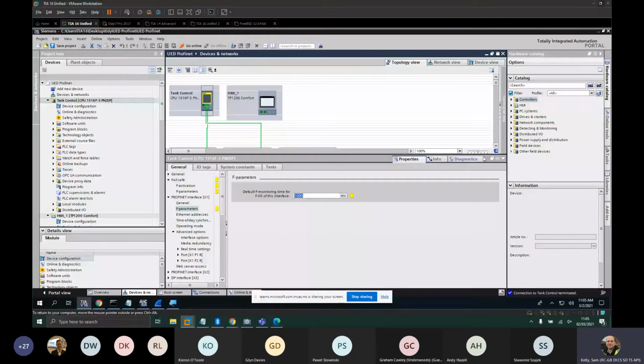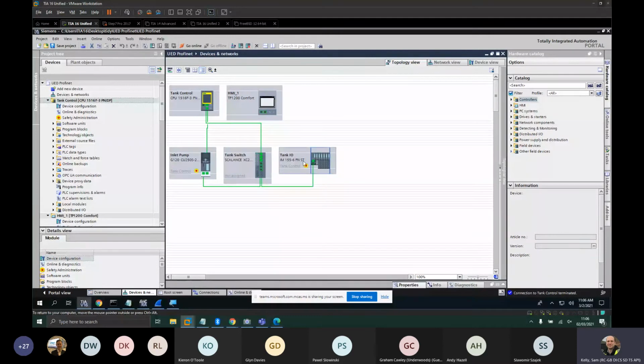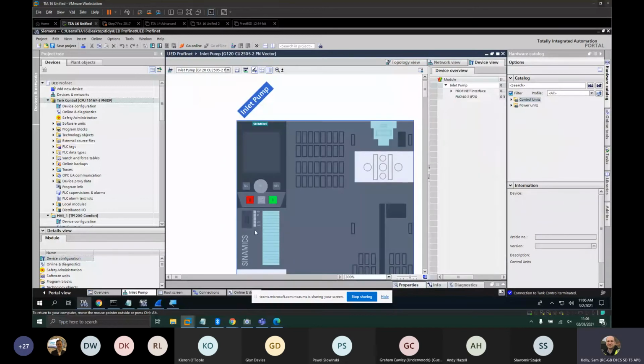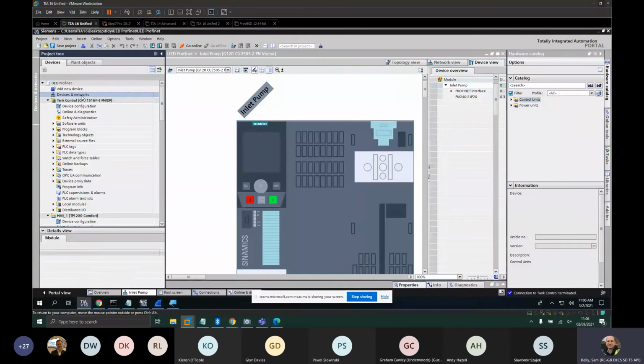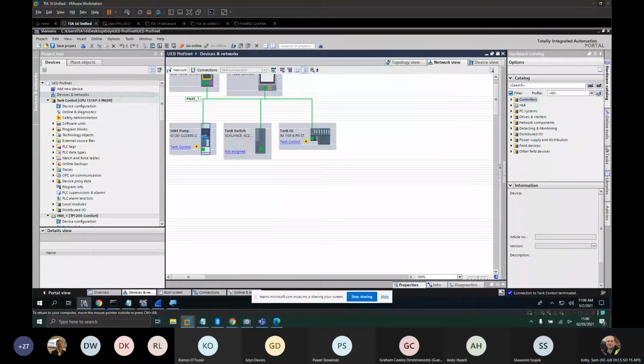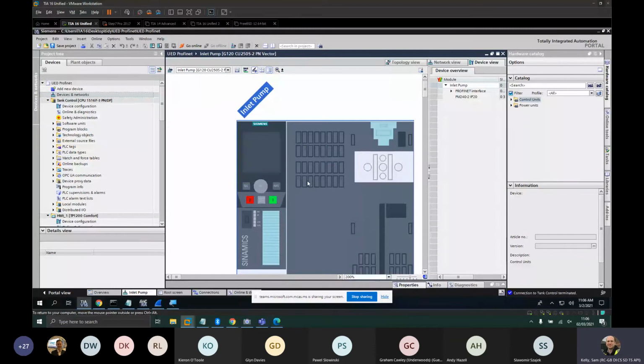Okay, also I'm doing safety, evaluating an e-stop on here and actuating the safe torque off on here, all over ProfiSafe. So the G120 as default can support failsafe. A lot of customers would do the failsafe by wiring into the I/O on the front of the panel, but because there's a Profinet session, let's do it over Profinet. So there's a couple of things that you have to do. So if we just look at the telegram configuration of my inverter,